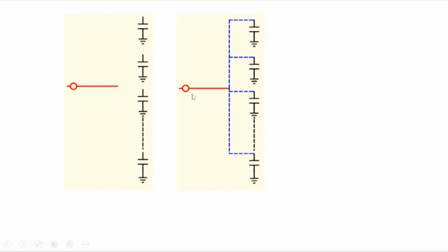So basically, you cannot have that many wires coming out. We said wires are only in the hundreds. So let's say there is one pin coming out of the memory, and through this pin you want to read all of these capacitors, either program them or read their values. If we directly connect them, then you're shorting all the capacitors together, and if 1 is stored here and a 0 is stored here, they'll all mix up and you lose the data. So obviously you can't do that.